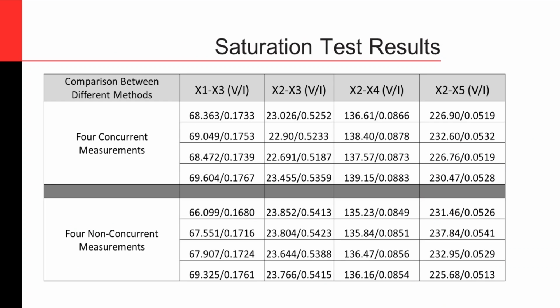One time you do the test for a C800 type CT, it comes back and says the knee point value is 796, which is pretty close to a C800 or 800 volts. It's a pass. The next time you do the test, it's going to be a different value. It's not going to be 796 again. It could be 812. Is that a bad value? No, it's not a bad value. It is somewhere around 800.